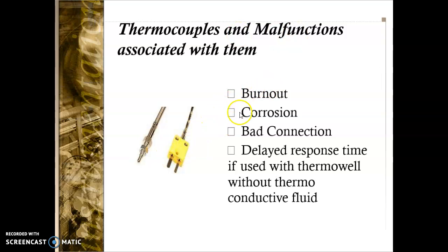Thermocouples. The thermocouple itself could burn out. It could be corroded. That's, again, materials of construction, the right materials for the right application. There could be a bad connection. Now remember too, if you have a thermocouple in a thermal well and you don't have a conductive fluid, that could give you some wrong readings. This is an installation issue, so you'd have to look at that as well.